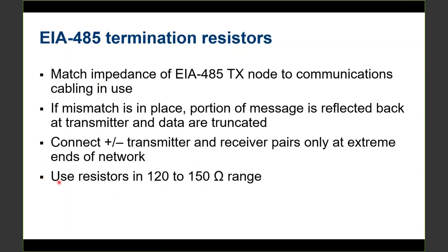But from my experience, whenever we have communication issues on 485 networks, that's usually one of the first things people want to try out, putting in a termination resistor. But it probably is the least common in my experience, the issue has usually turned out to be something other than it needing a termination resistor. So that's all I'm going to say about those.